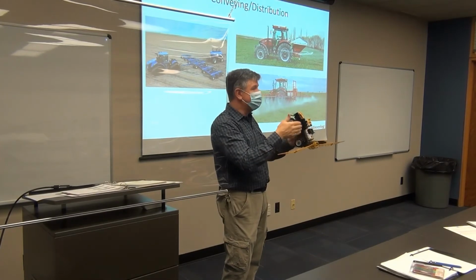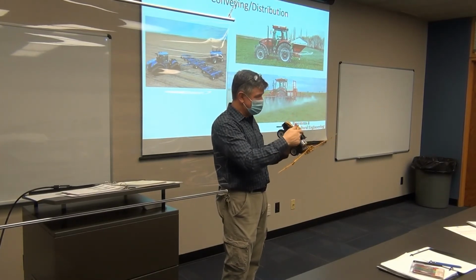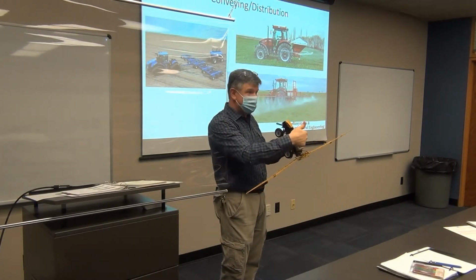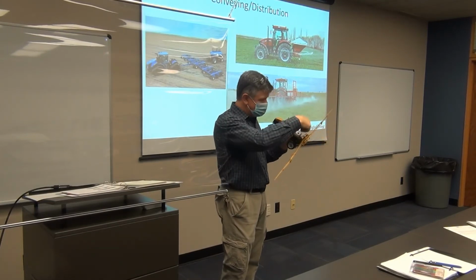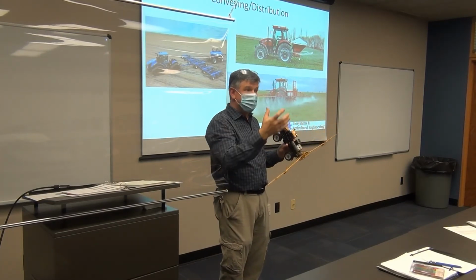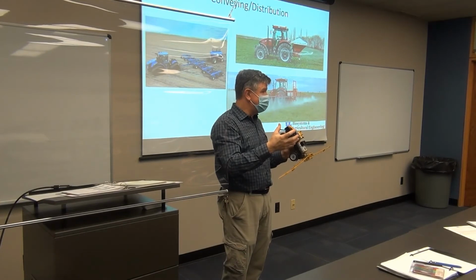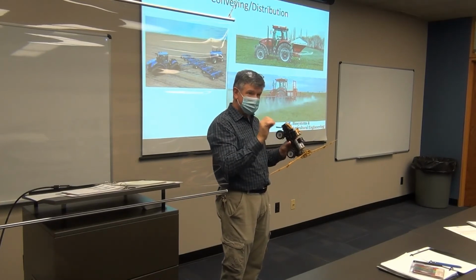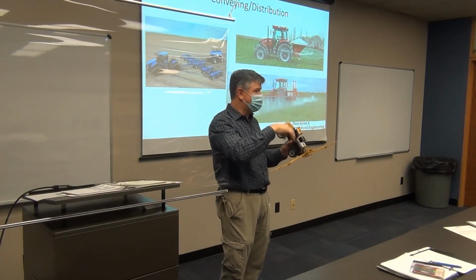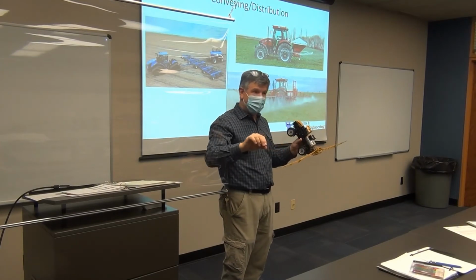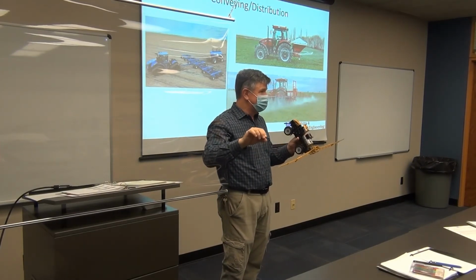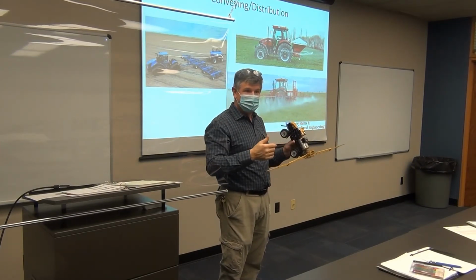So we're trying to move that injection further downstream. I'm going to have some other tanks, like this black one on top, and you put them in different places on here. That's where I'm going to put the concentrated chemical, and then I'm going to meter that concentrated chemical into the water stream as it's going out to the booms. And now I don't have to clean all that stuff out.